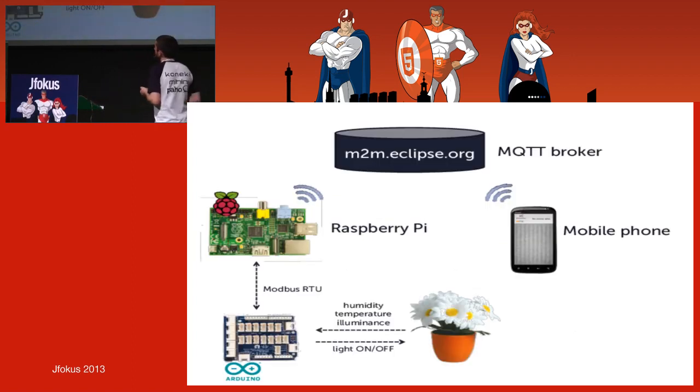I will use a Raspberry Pi for doing all the embedded logic of getting the data out of my sensors and pushing the data to the server. And my wireless gateway is basically going to communicate with another kind of open hardware, which is an Arduino. And I know that eventually my greenhouse equipment will be talking using an industrial protocol. So why not use this protocol right from the beginning? I will use a Modbus stack on my Arduino, so that in my Raspberry Pi, I can start using the Modbus API to get the data from the sensors.